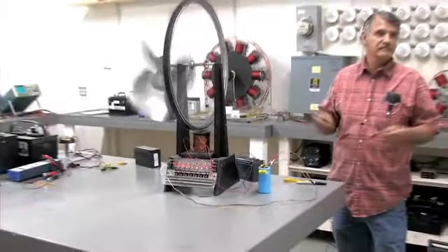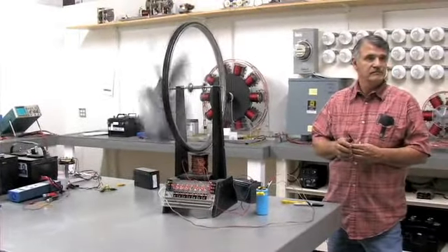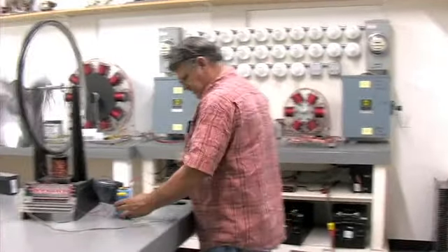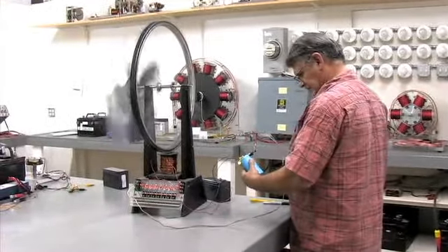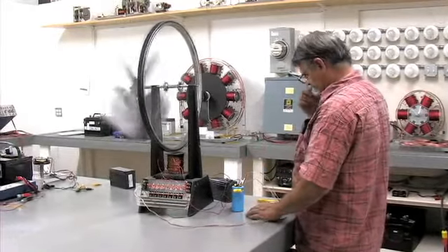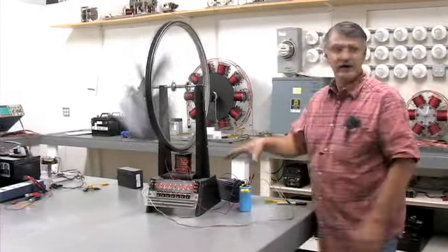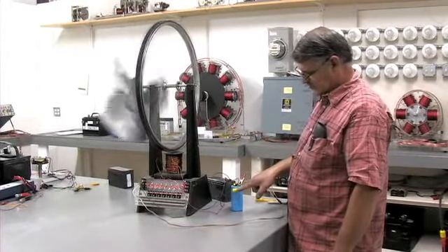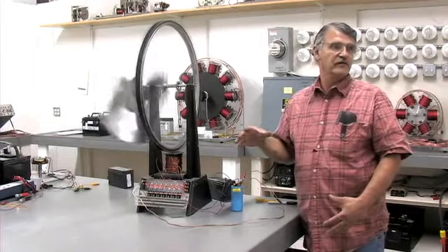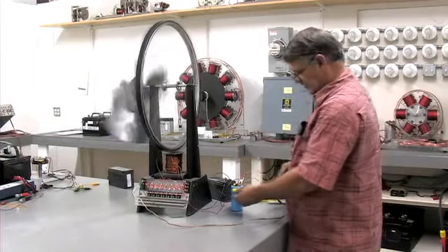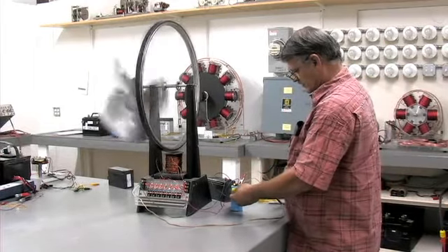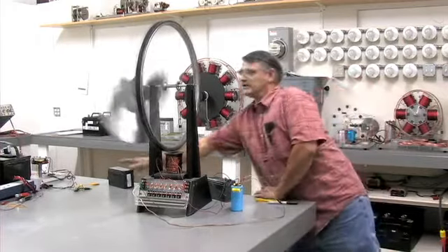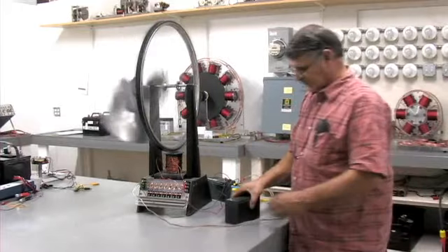Got it? So the potential you're getting across that capacitor is what, about 400 volts? Yeah, about 100. This capacitor is probably about 75 or 80 volts here with this capacitance. If you were to use this 0.1, it'd be like 400 or 500 volts, much more than what this capacitor could take. So basically, you're going to store the charge, and you're going to repeat this operation over and over like this.